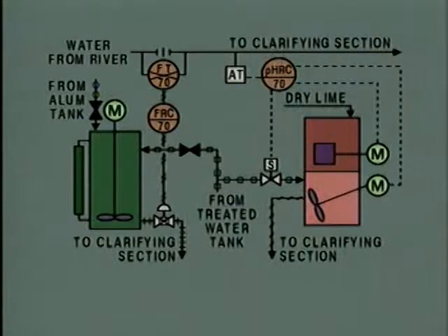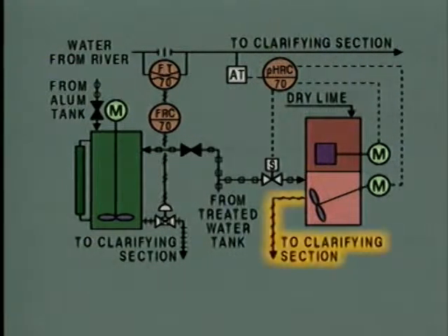It's common to have to trace flows upstream to other systems to locate the causes of problems. This often means that more than one P&ID may be needed to troubleshoot a problem. For our problem, we'll need to look at the P&ID for the chemical mixing section. This P&ID shows the components of the chemical mixing. This symbol represents the hose to the flash mixer in the clarifying section.